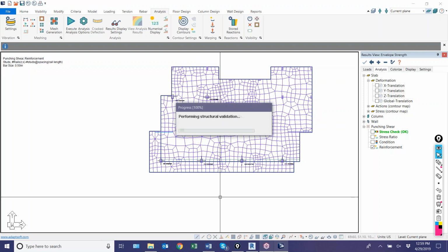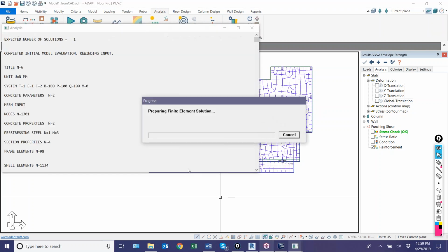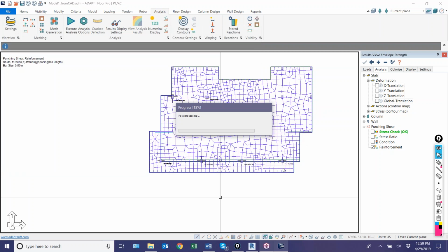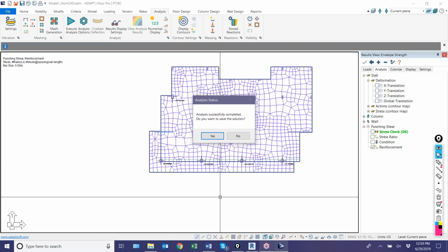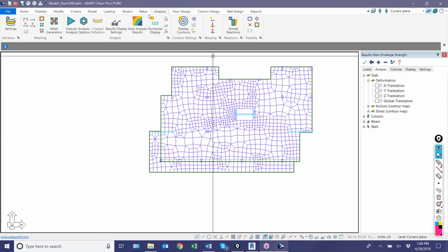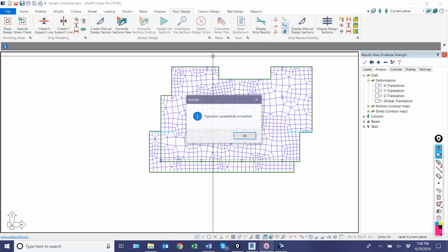Now what this will do, having the beam in place, these 4 columns along the balcony will no longer require reinforcement, because now in this case, the program assumes one-way shear controls, and it doesn't check punching shear for columns that are connected to beams. So if we go back and run the punching shear again, we'll just rerun punching shear.